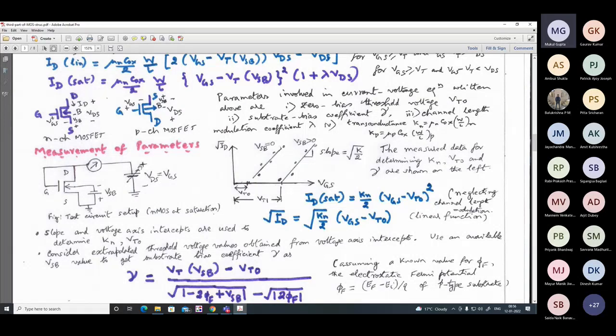As far as the lowest value goes, it can be as low as the threshold voltage. Suppose the threshold voltage is, say, 1 volt. Then the least value that you can bring up and get measurable current will not be 1 volt, it will be somewhat higher, because if you have VGS exactly equal to VT, the channel has just started to appear. So if you remember the plot of the output drain current versus VDS characteristic, it starts from a very small value of VDS and it proceeds.